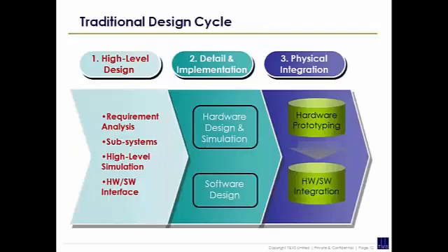So the co-verification idea was that even before, okay, this is interesting. Some people said that let us do co-verification when the RTL is frozen. But some people claim that it is better to do co-verification even before the RTL is frozen, because we have scope for making modifications to RTL. If we find something, we still have the scope to make modifications in RTL and still have the fix in hardware rather than making a software patch.